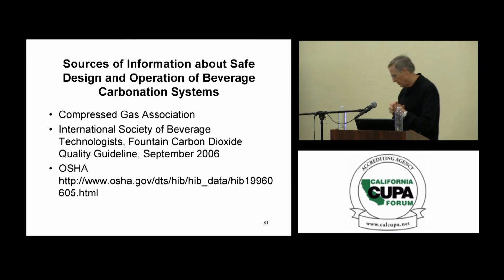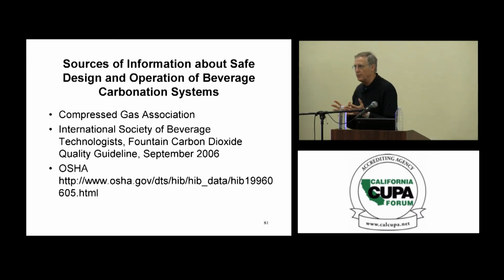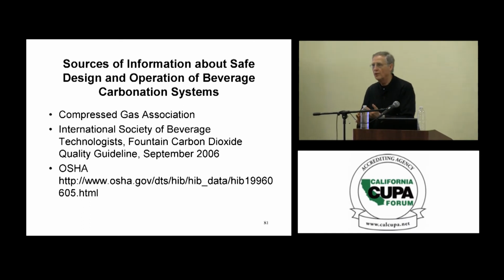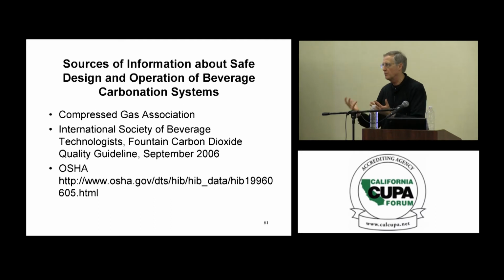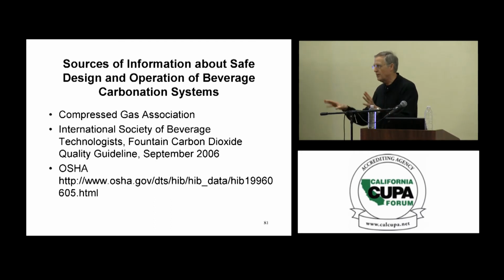Why do we use inert gases for blanketing? Typically to prevent degradation of a product or to prevent getting into the explosive range. We'll talk a lot about that when we get into flammable gases at the next session.